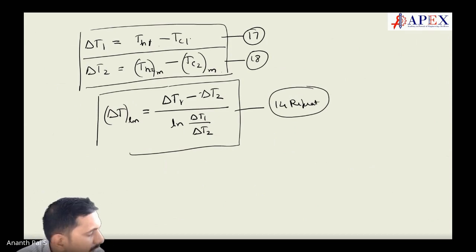Now, the second case which can happen is condensation. If there is a fluid which is condensing, or a fluid which is evaporating, in both cases the concepts of counter flow, parallel flow or cross flow don't hold good there. What do you call cross flow or counter flow? One temperature is the same, is it not? So this comes as a separate case where we have condensing or evaporating, or heat transfer with phase change. Write this down.